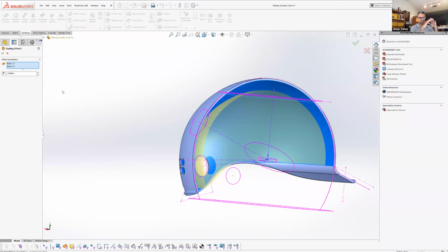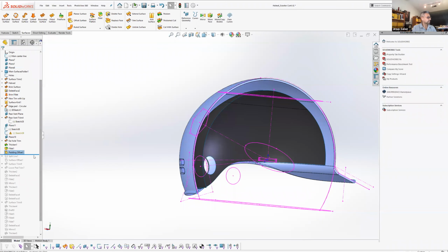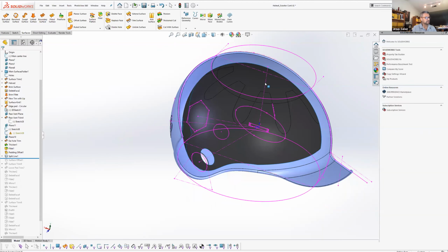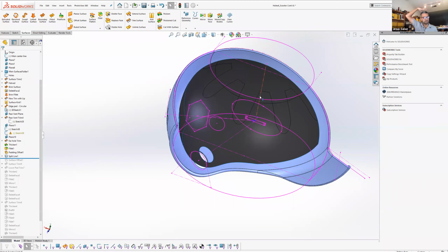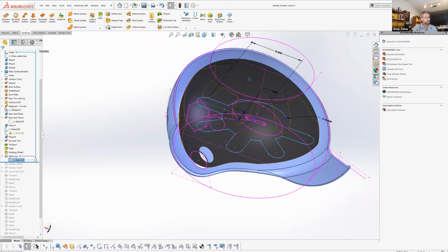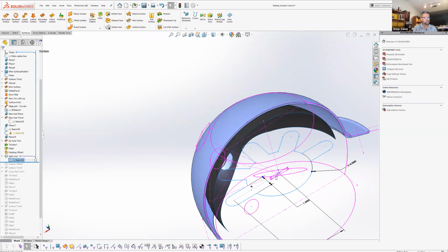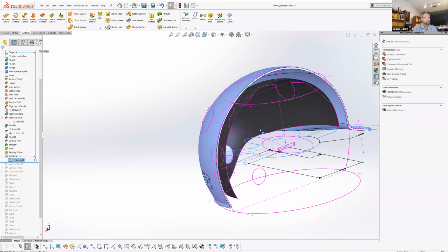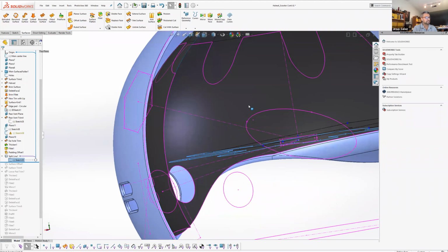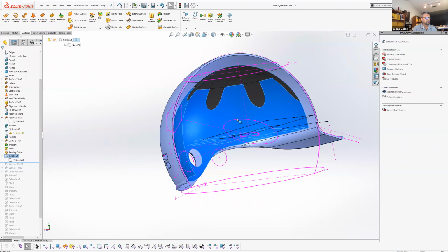And obviously this follows the shape of the helmet exactly, because I just did an offset surface. So then from there, I wanted the star shape up on top. So I created that as a sketch. There it is. And I just did half of these spikes here from the top. So this is getting projected downward. I didn't trim it yet,